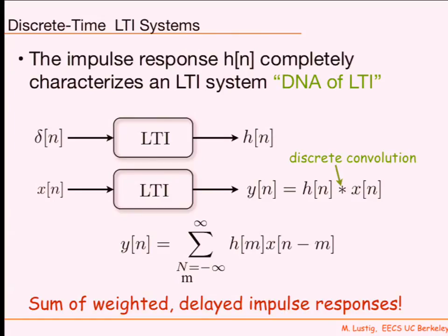So discrete time LTI systems are characterized by this wonderful thing. If you have an LTI, linear time invariant, or linear shift invariant system, why would I say shift? It could be space. It doesn't have to be time. So don't focus yourself on time. A lot of people deal with space. Linear time invariant systems are a class of systems that are very powerful and very important. There's one thing about those systems that makes them amazing to analyze, and that's the impulse response. The impulse response of an LTI system is kind of like the DNA of it. Once you know the response of an LTI system to an impulse, you know everything you need to know about that system.